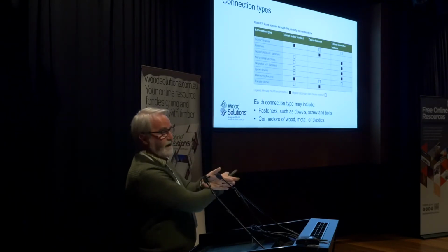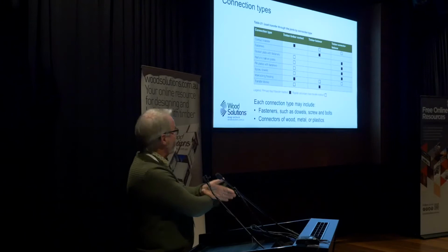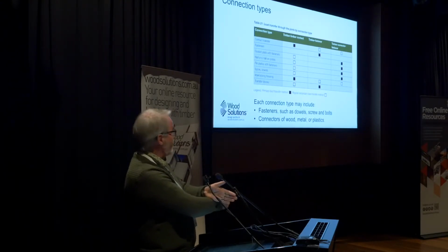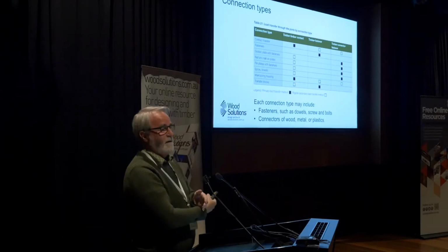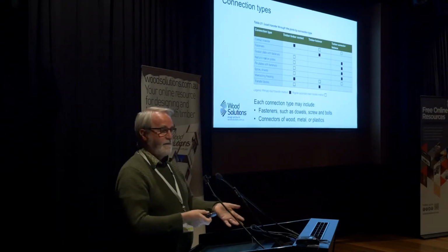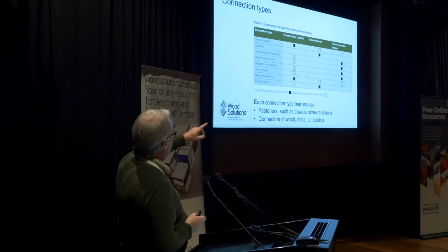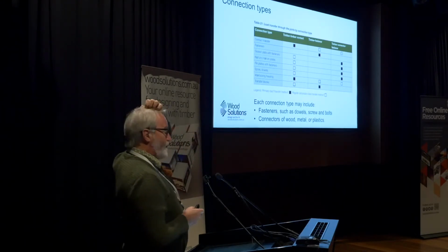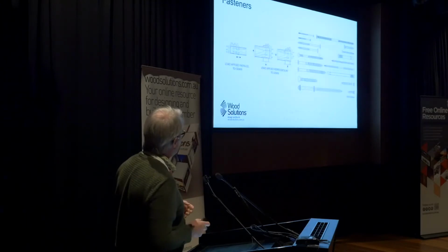If we skew nail it, we've got a timber to connector system, timber to fastener system, and we're using that to locate it. We may also strap it, and so we're using the strap as a connector. So where we say we've got primary load transfers through the black box, the other one is through the secondaries.